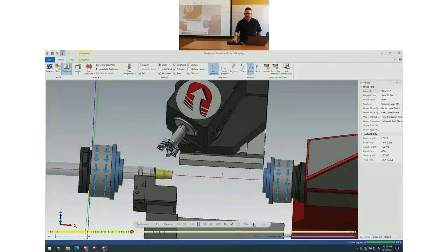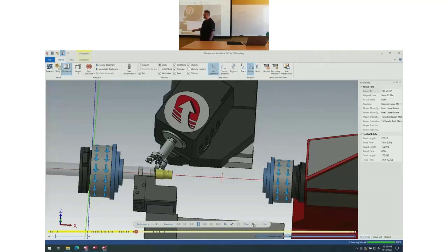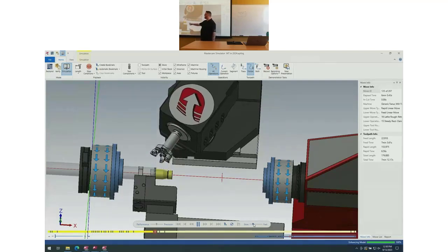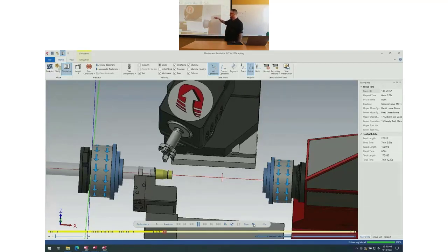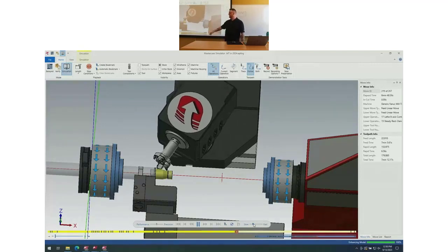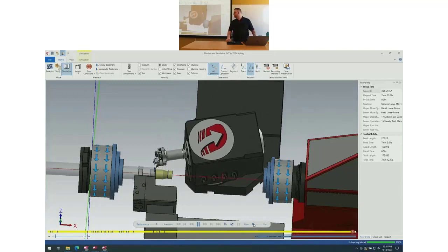And then we've got our B-axis angle in here. So it's going to come in and cut this way instead. And then I think it's going to switch to a different tool, because I think this is a D and I'm going to switch to a V. So it spins that around, and then we'll B-axis contour to finish it off. So we'll actually see the whole thing spin. So none of that was possible in 2017 at all.